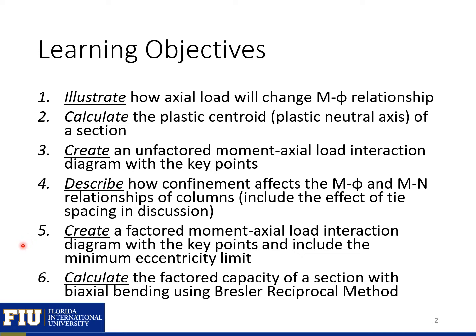Create a factored moment axial load interaction diagram with the key points and include the minimum eccentricity limits, and calculate the factored capacity of a section with biaxial bending using the Bresler reciprocal method.